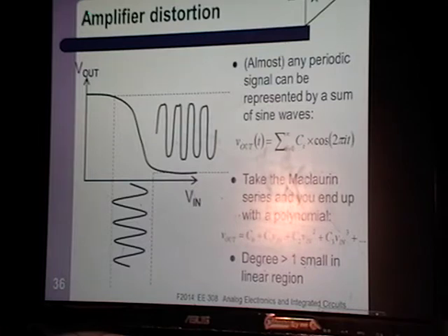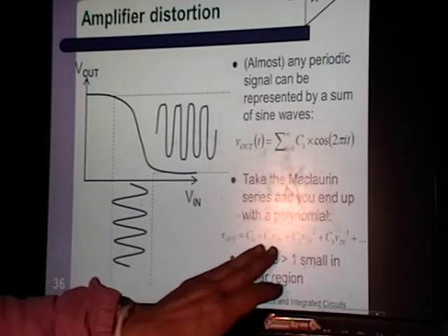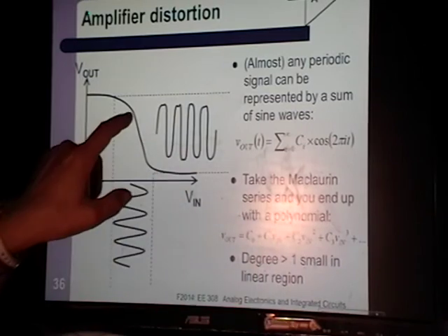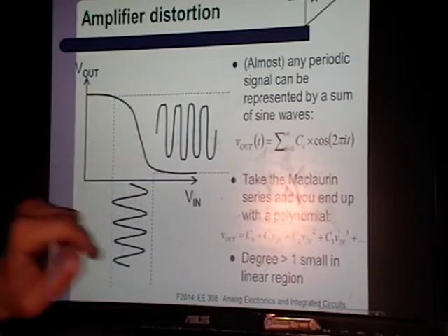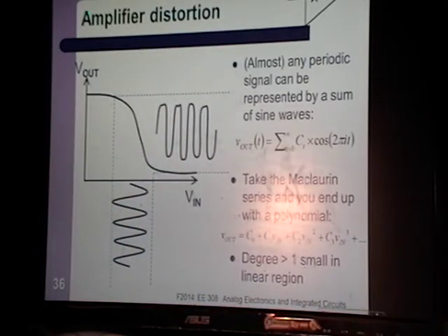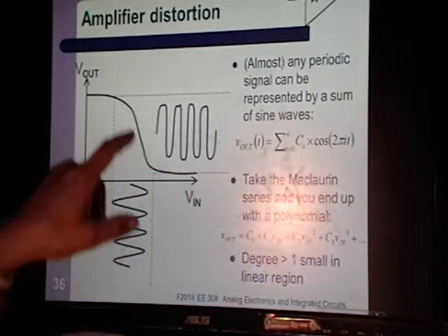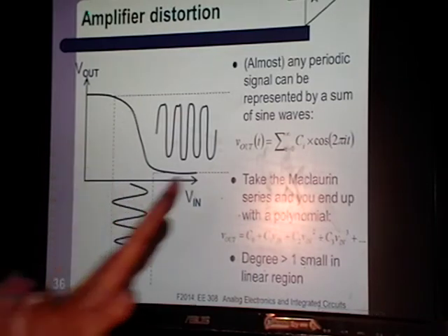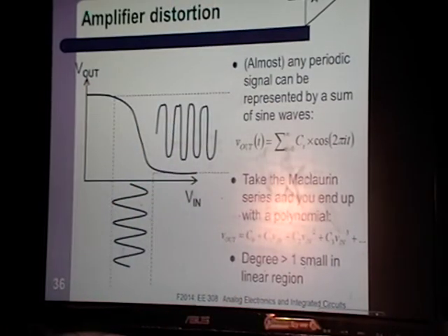Again, to make the math easier for humans, and really all the small signal analysis that you do on paper, it's all going to be in a region that is pretty linear right here, so we can throw out the rest of these terms and not have too much of an error. We'll still have an error because these C2, C3 are not zero in this region, but again, just like the current equation, it's an approximation. It's useful, so we can on paper do some calculations and see what our circuits are going to do.